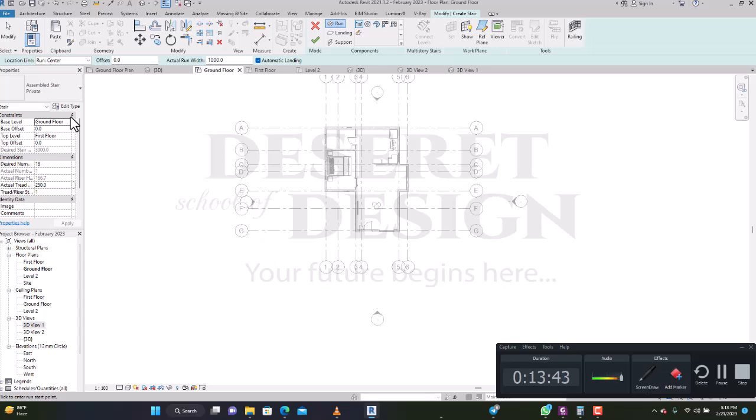Now I'm connecting this wall to this level, but I'm also setting a base offset. Now the base offset says maybe I don't want this wall to exactly be on the floor. I want an offset value of, let's say, 300. So it is like this, but it is still connected to this level. So wherever I move this level, if I move it down, it will still maintain the 300 offset, because we are connecting it to a level, but you are still putting an offset value. Same applies to the top. Do you get it? It can either be more or less. Do you get it? Okay. So that is what we call the base offset.